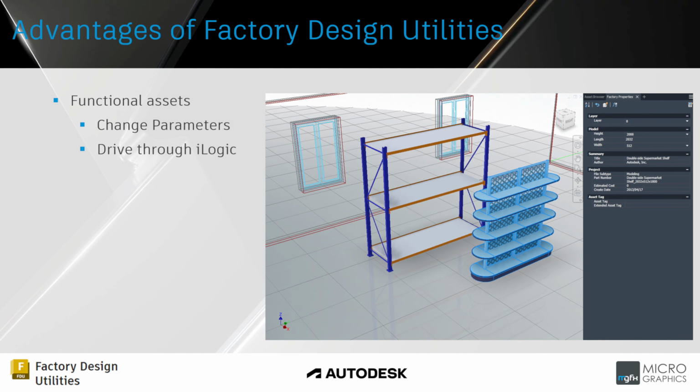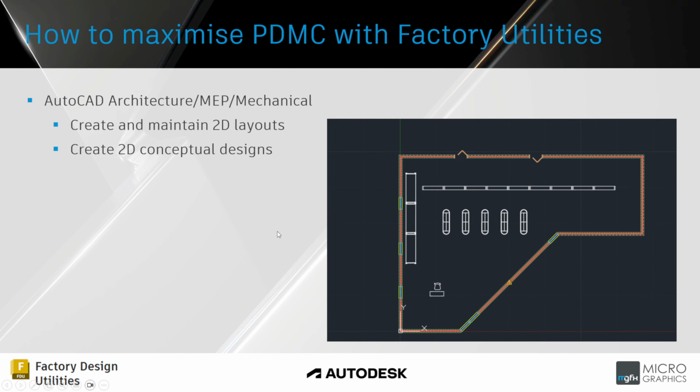So I brought in the one shelving and configured it to be 2,000 millimeters high, I think, with a certain width and a certain depth, and then I just copied it using the copy array. Same with this shelving over here, and with this one I also did an array, I think with columns, and rows being 1. Once that's done, we've created our layout, our conceptual design. That's kind of where we think we want it to be.